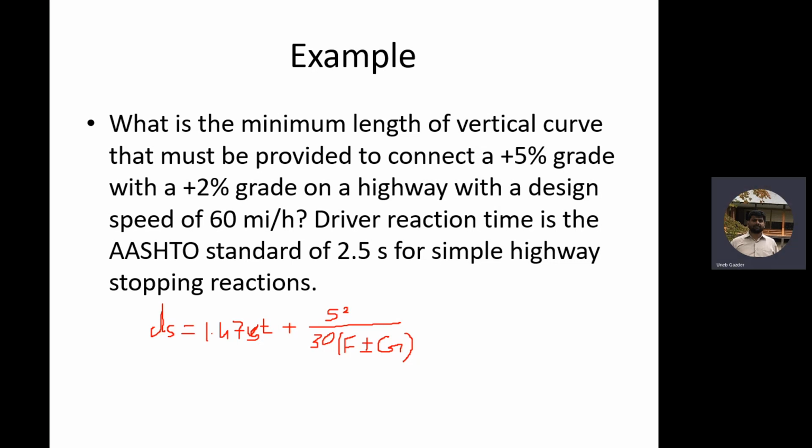Okay, this is what they call skid resistance. That was side friction. So this F does not depend upon speed. It depends upon the deceleration and gravity, A upon G. This is capital F, which is A upon G, deceleration upon gravity. The one which you use for calculating radius, that was small f, skid resistance. For that we have a table. But this is A upon G.